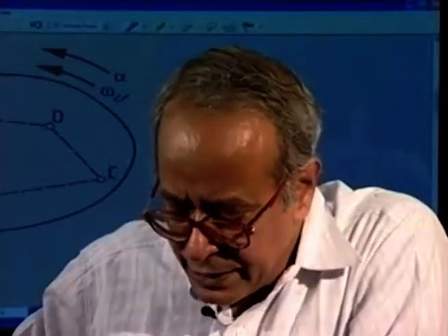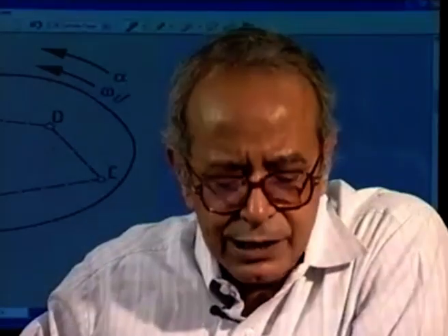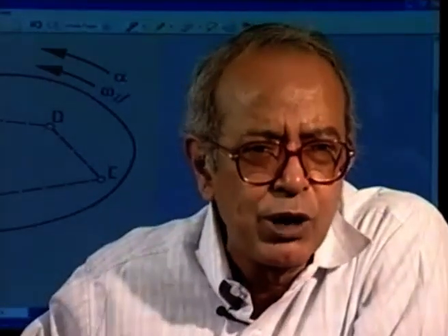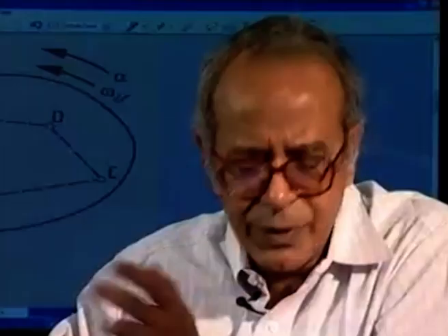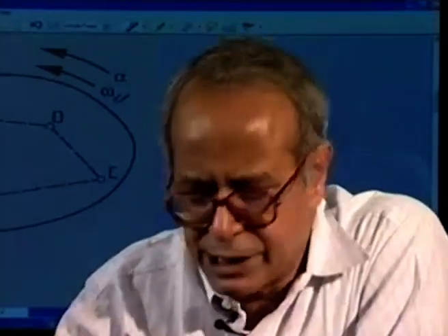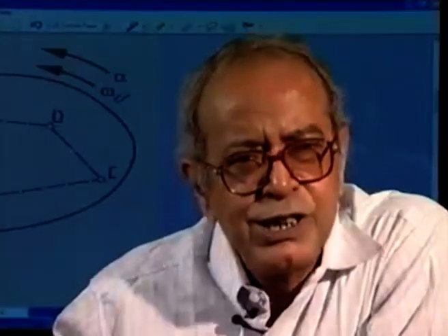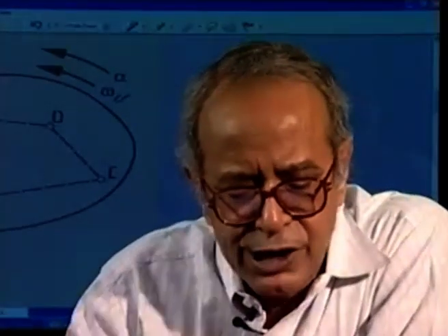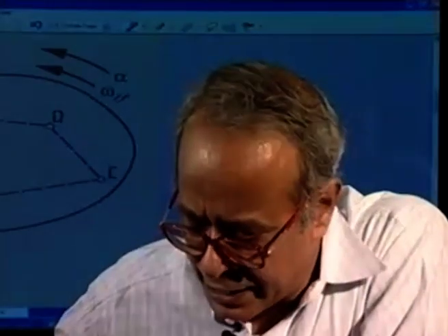What we will find is that if the velocity or acceleration of 2 points of a rigid body are known, then for any third, fourth or fifth point I need not do an elaborate analysis. I can use this concept of image, which is nothing but a scale drawing of the original configuration or kinematic diagram.